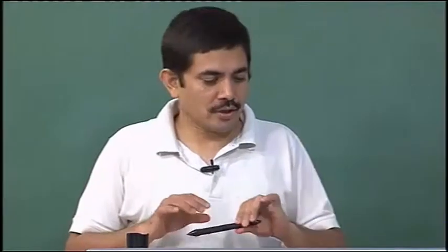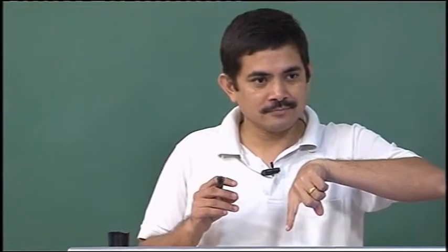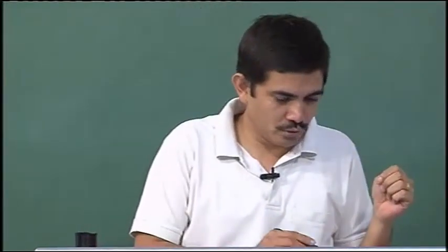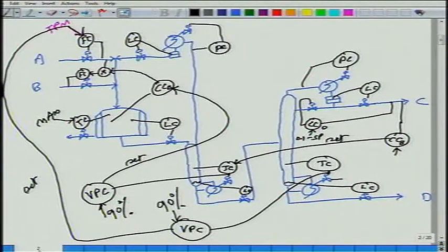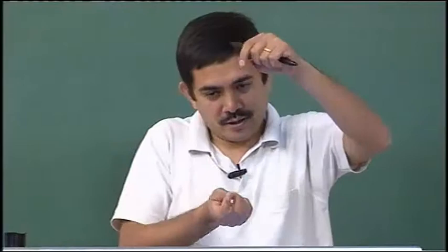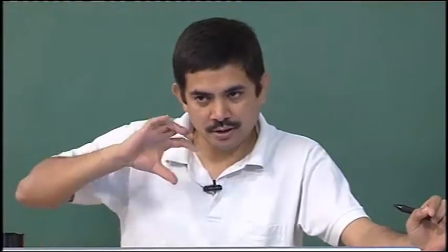So, if your throughput manipulator is something that is in your hands, you are free to choose it. It is not being told, fresh air is so much, process it. Then it is not in your hands, and you are forced to do what I just did. Throughput manipulator was not in my hands. But if it is in my hands, I choose it at the last constraint to become active, and I put in place a control system that ensured that every active constraint actually became active. I was able to operate very close to it and did not require a large back off. That is all a matter of proper structuring.